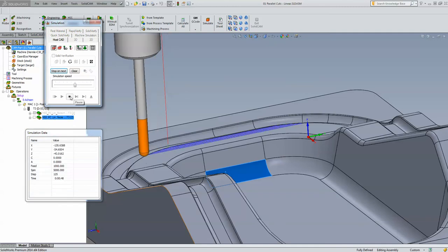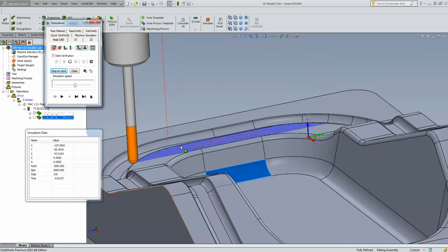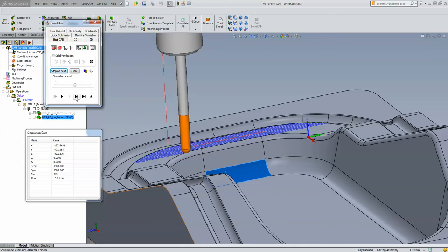Okay, in the beginning it's starting back and forth over there. Now as it gets to this area over here, let's see what happens. You can see the tool going over there. Note the feed 1,000. Now it's going to arc up off the part itself, go up, and now look what happens when it goes across. It's running at my rapid feed rate. Now, when it goes back down into the part itself with my lead in feed rate, now it goes back to 1,000, going back around the part over there itself, leaving out the part,